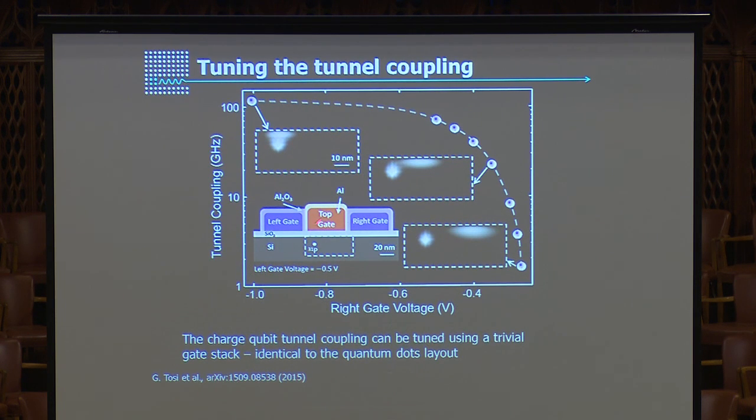This is something we know how to do. This is an MOS quantum dot. That's exactly the stuff that Andrew was showing you yesterday. We know how to do that. It's a very different story than how to do a J gate aligned between two donors 15 nanometers apart.